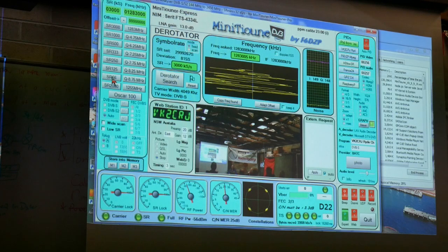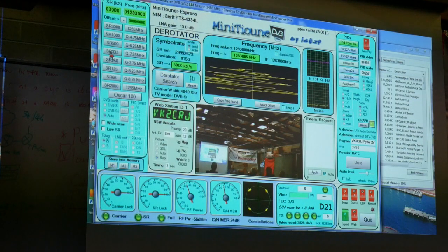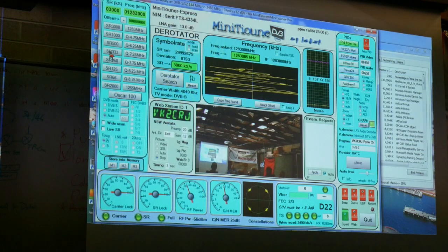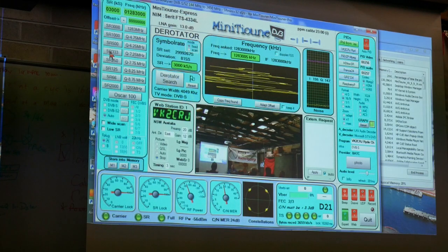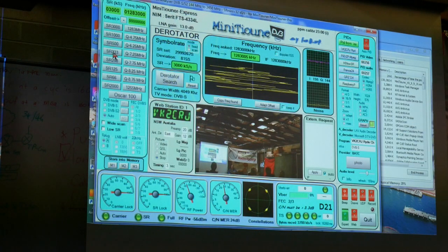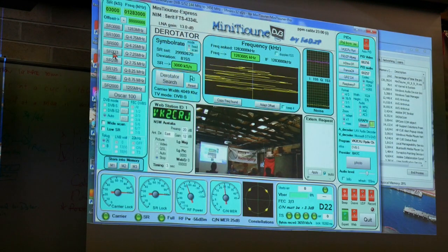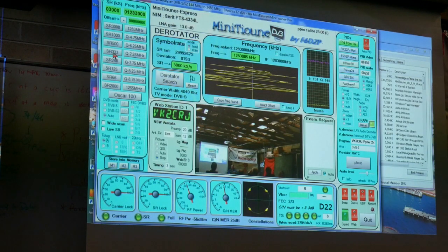And so we've been playing around here in Sydney to try and get direct signals, because now we haven't got a repeater. It's a real struggle because there are so many hills in the way. But we have succeeded, myself and John, over an awful path, in getting a signal through at 333 kilosymbols per second on TV, whereas an FM signal over the same path, me to him, was an S1. And that was me just running a couple of watts. But with a lower symbol rate, you can reduce your bandwidth and come down to VHF and then get in easily. Yeah, you can. There you go.